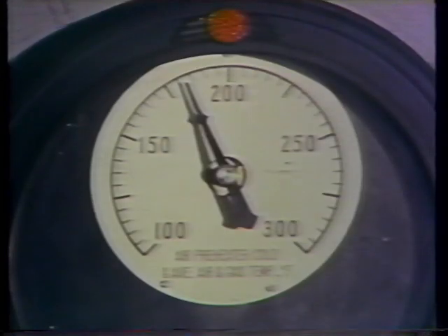The amount of voltage you get at these terminals depends on the difference in temperature between the hot and cold junctions. The voltage produced by a thermocouple can be used to operate a meter or a recorder. That voltage is directly proportional to the temperature that the thermocouple is measuring. That's why the meter or recorder is able to indicate what the measured temperature is.